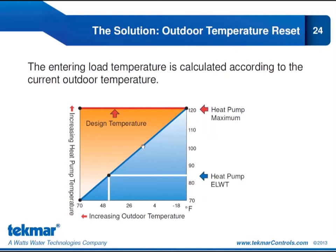We're going to see our entering load water temperature, or our tank target, decrease as the outdoor temperature increases. So instead of maintaining 120 degrees regardless of outdoor temperature, regardless of the heat loss the building will experience, we're going to vary based on the estimated heat loss from our building.